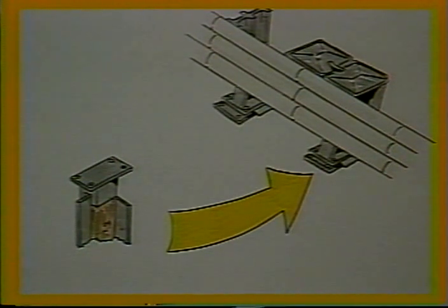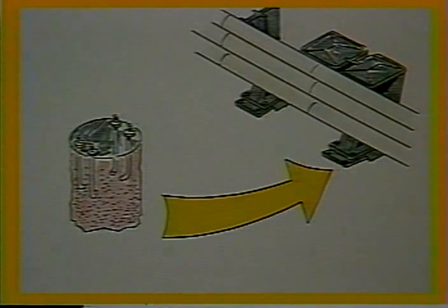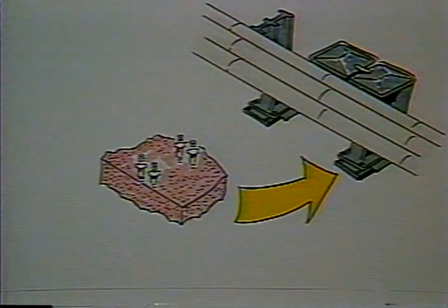4 basic anchoring alternatives are suggested by the manufacturer for the system. The first option involves driving a wooden post with a platform attached to the top of the post. The second option uses steel I-beam driven into the ground to anchor the unit. The third option calls for embedding L-bolts attached to the slip bases in 4,000 psi concrete footings. The final alternative uses expansion-type or flush-type anchor bolts to fasten the Sentry to a 4,000 psi minimum concrete pad.